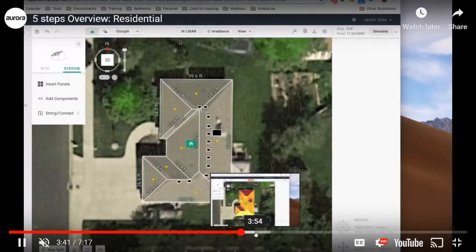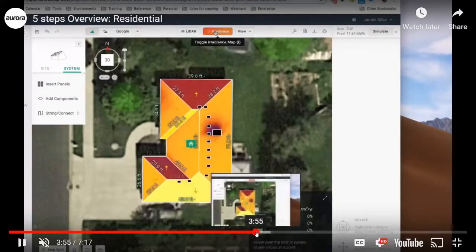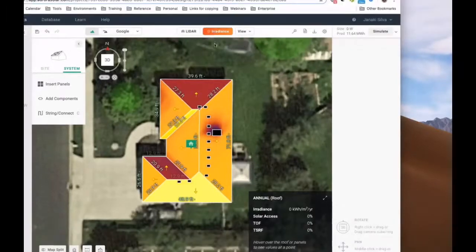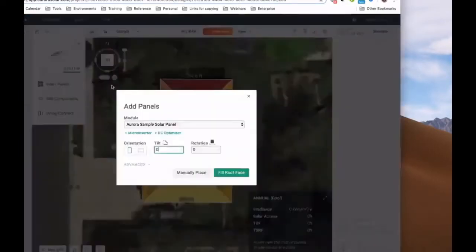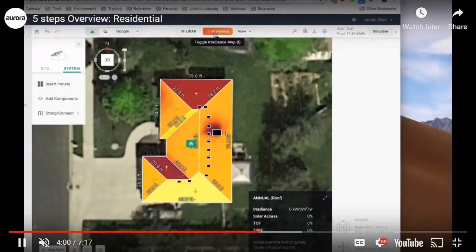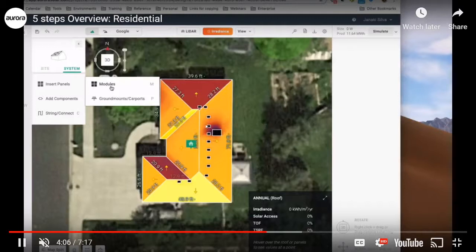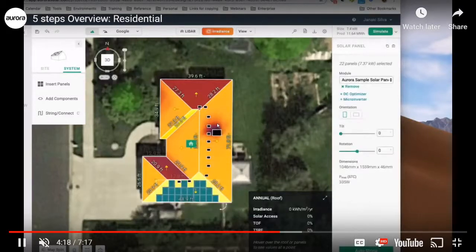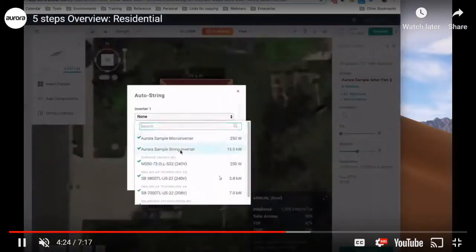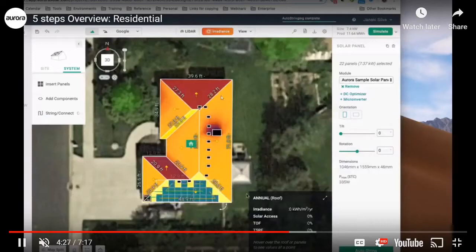And then here they're drawing obstructions. And so now they're doing a shade analysis. And so obviously the south side works well, and the north side is the least sunny that I do. But we can also note just how large this area around the chimney is, and so we can kind of say, okay, well, is that going to be, if I stay out of this area, maybe I just want one array surface, or knowing that I'm going to have a broken array surface if I go into this larger area.